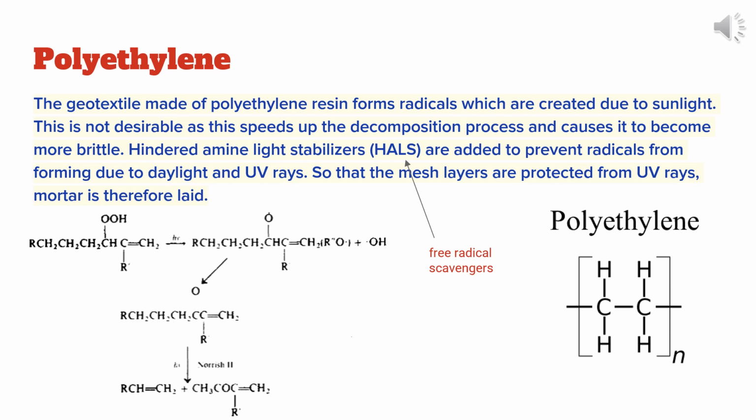Weathering leads to the deterioration of the mechanical properties of the geotextiles, which obviously is undesirable when geotextiles are needed to increase the strength of an area whilst retaining their own. The behaviour of the geotextiles is highly dependent on their chemical compositions. Hindered amine light stabilizers enhance their resistance to weathering. Higher amounts of HALS used will therefore result in the best protection against weathering.